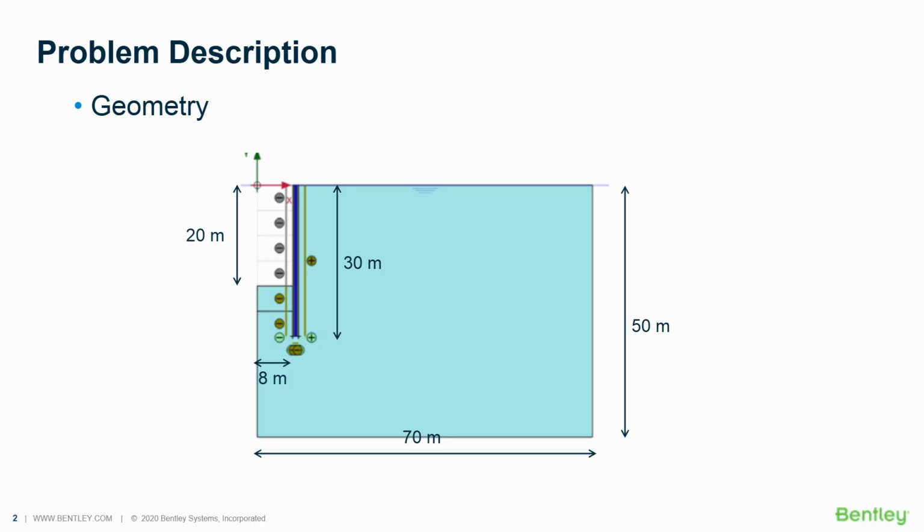We have a shaft here, which is 30 meters long and 16 meters in diameter, and we will try to excavate it to 20, even 25 meters at some point, with consideration of dewatering. You see the water level has been placed completely at the top. We will try illustrating this dewatering using two different methods. The first one will be the phreatic level, and the second one will be the groundwater flow.